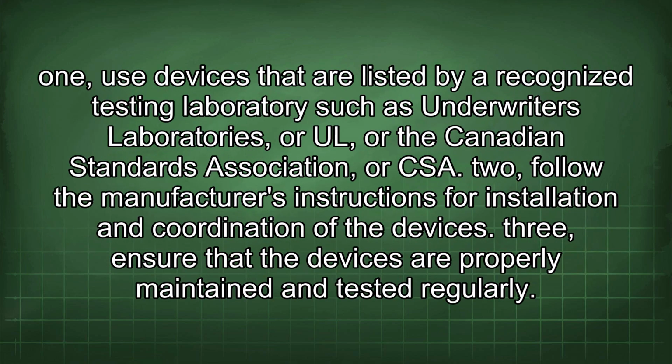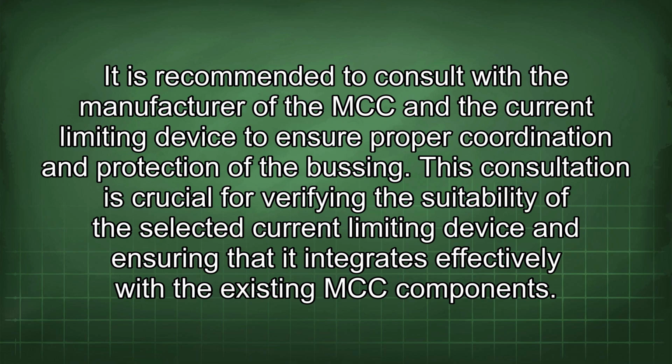1. Use devices that are listed by a recognized testing laboratory such as Underwriters Laboratories, or UL, or the Canadian Standards Association, or CSA. 2. Follow the manufacturer's instructions for installation and coordination of the devices. 3. Ensure that the devices are properly maintained and tested regularly. It is recommended to consult with the manufacturer of the MCC and the current limiting device to ensure proper coordination and protection of the busing.